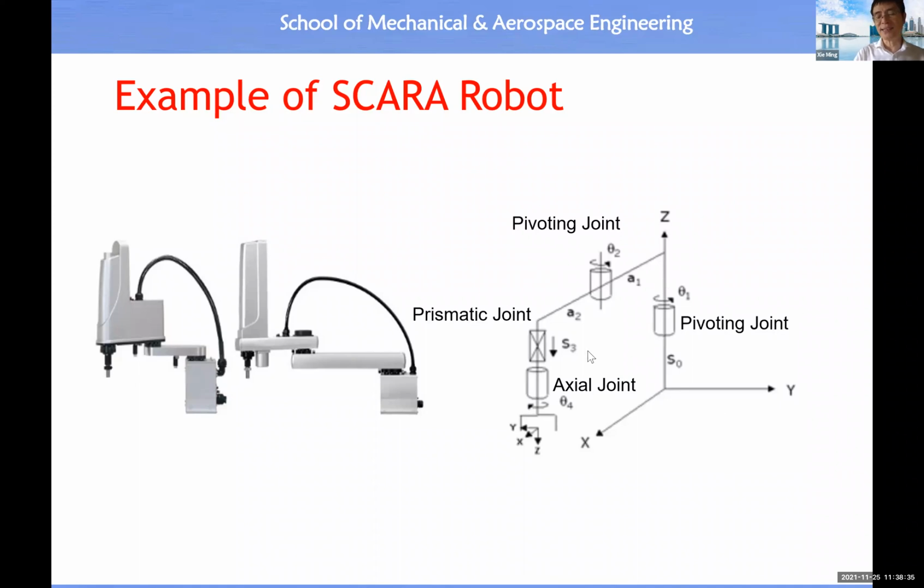This is a graphic representation of a robot's mechanism, because a mechanism is a linkage which permits relative motion between 2 adjacent links. This is different from a structure. A structure is a static linkage, in which there is a restriction of relative motion between any pair of 2 adjacent links. We do not want the structure to move.